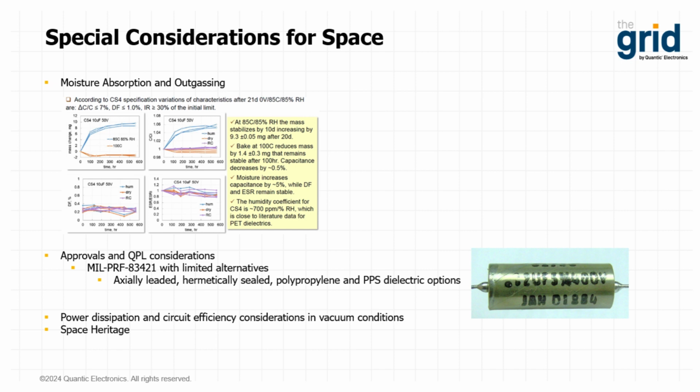But the MIL-PERF is specifically for hermetically sealed and axial leaded parts. By hermetically sealing parts and making them axial leaded, this restricts you to a wound technology. This increases the overall size of the capacitor by adding a very large case with glass to metal seals.